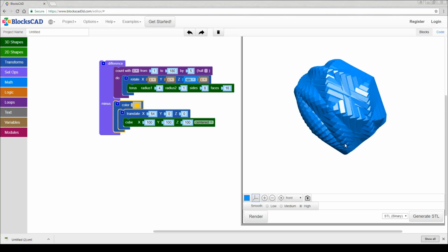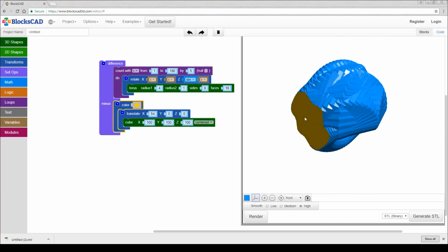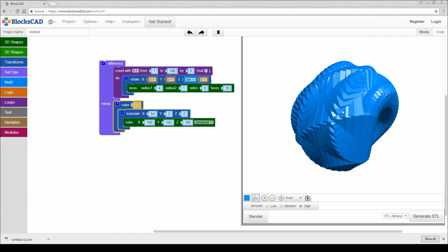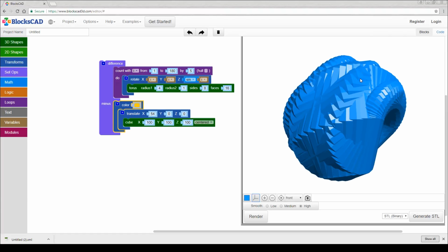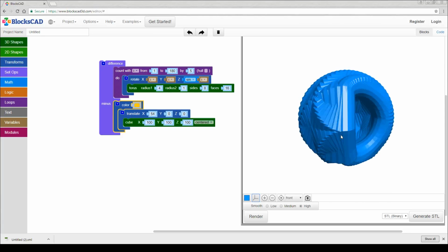Alright, the render is finished and we can see our excellent shape on top is preserved, but we have a nice flat base for 3D printing. If we're trying to print it from any of these, you'll probably find that you need far too much support material and the pattern is ruined anyway, so far better to give it a flat base and do it right the first time.